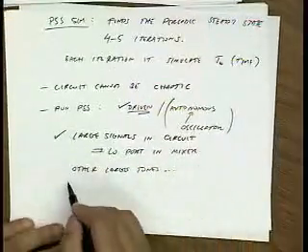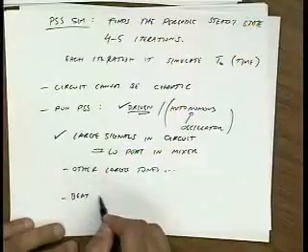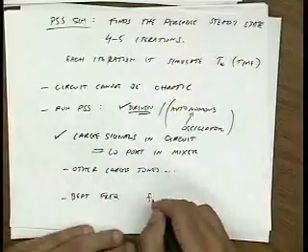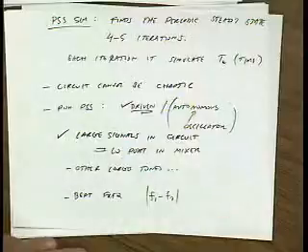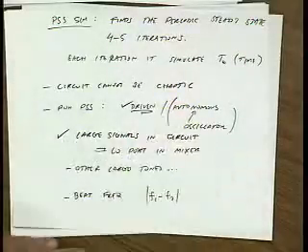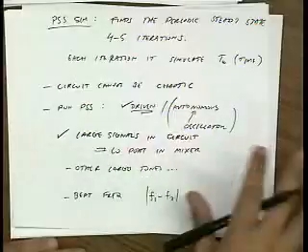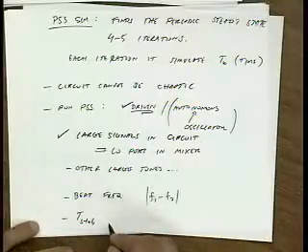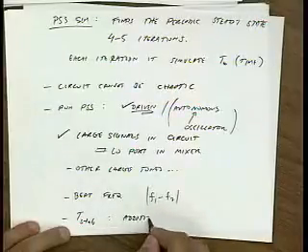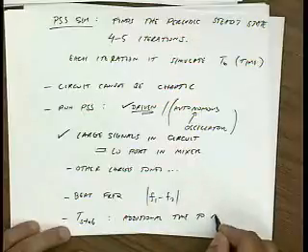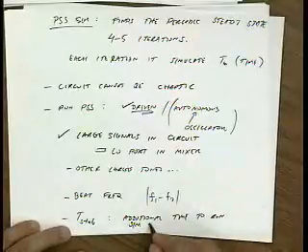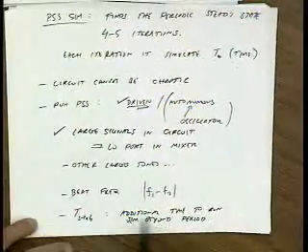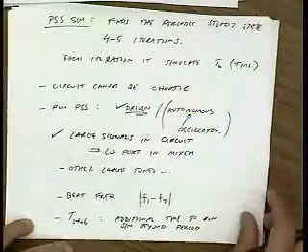Finally, you need to give the beat frequency. So for instance, if you have 2 large tones, it would just be F1 minus F2, right? But actually Spectre can calculate what the beat frequency is automatically if you give it more tones. Finally, you could give it a parameter called T-stab or T-stabilization. This is additional time to run simulation beyond the period. And this is useful for oscillators. It's not really that useful for mixers, so you can more or less ignore it.